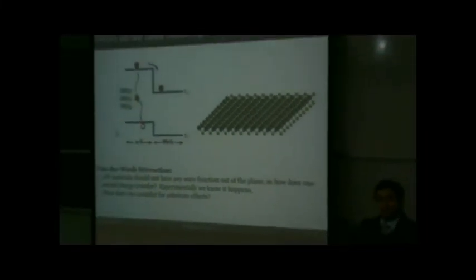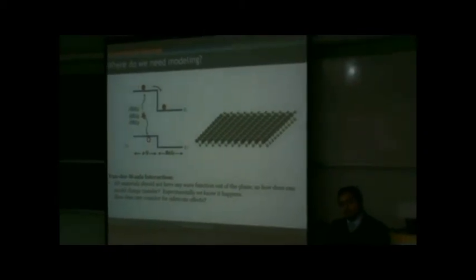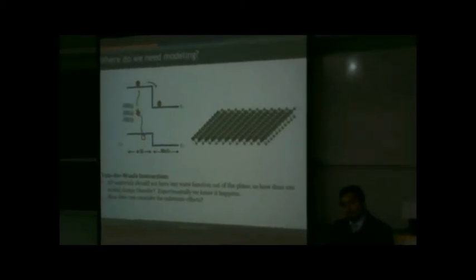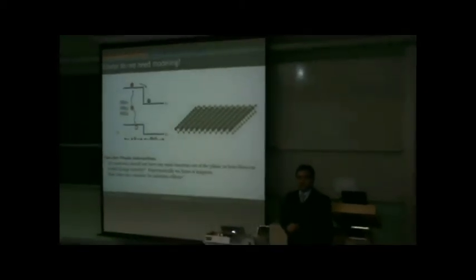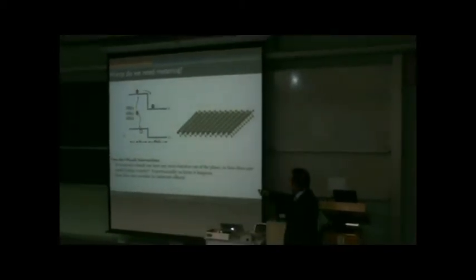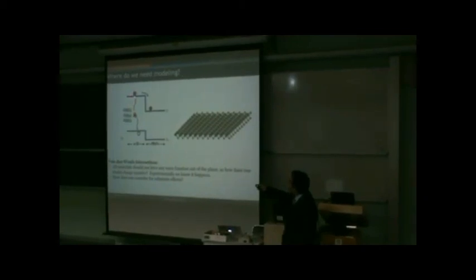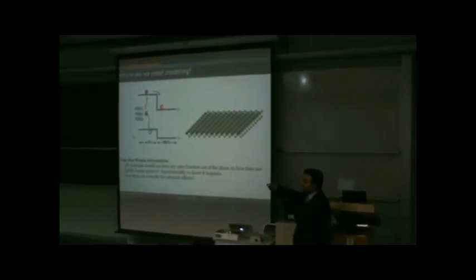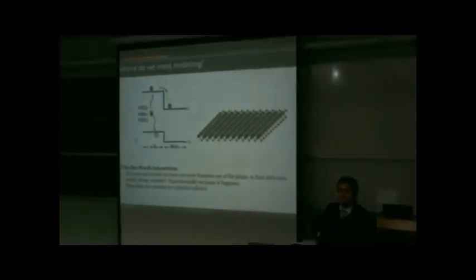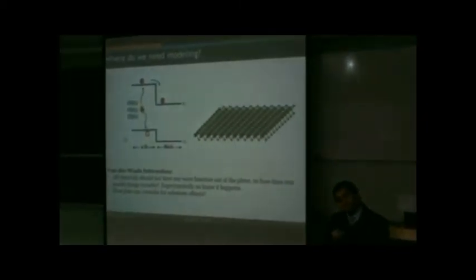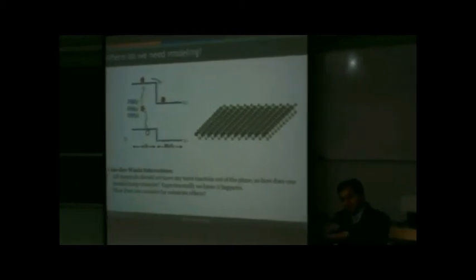No, intrinsic. But amorphous silicon is naturally n-doped. So it is almost like an n-n junction. The main thing is there is a built-in electric field here, which can separate the charges. So in spirit it is very close to having silicon and graphene on top.